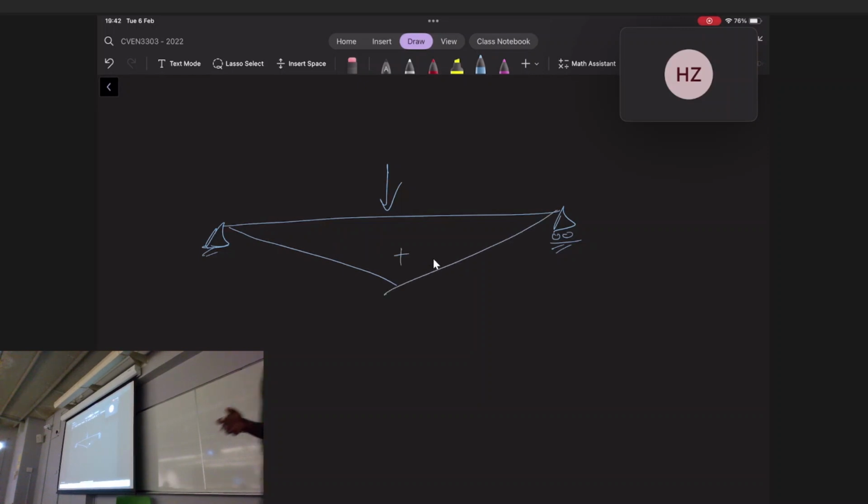Okay? But in reality, just to give you a heads up, like when you do work as a structural engineer, if that's what you pursue, if you're looking at bending moment diagrams, even signs don't matter. Like no one cares if it's like a positive or a negative moment. Like the sign doesn't matter. Literally, it's the shape. That's it. Okay, and which side it's drawn on matters a lot. So why do I say drawn on the tension side?